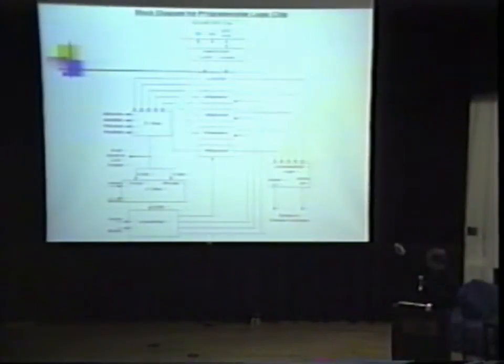However, if the 4 alarm registers here are chosen, the 16-bit number will be broken up into 2 8-bit numbers for hours and minutes. One of those 8-bit numbers will be chosen in this multiplexer based on the 2 minutes and hours increment buttons. That 8-bit number is then sent to the incrementer down here, which is incremented by either the hours or the minutes incrementer.